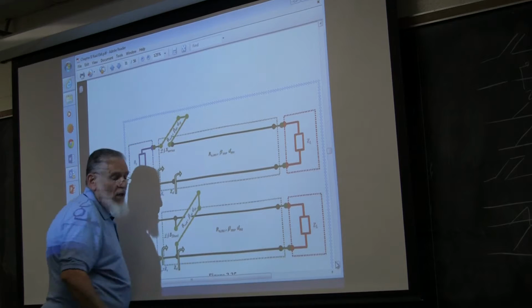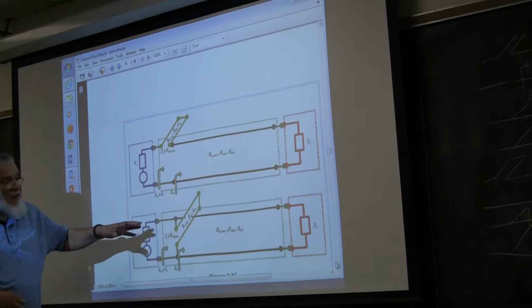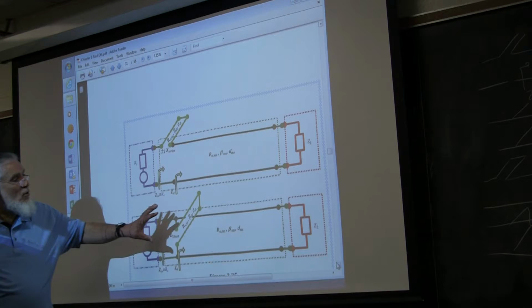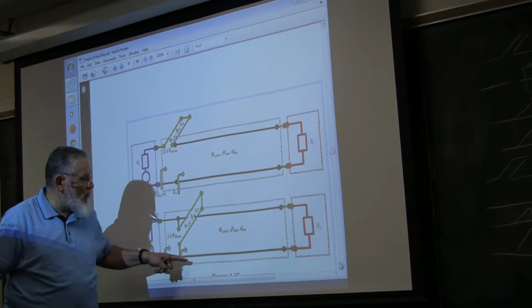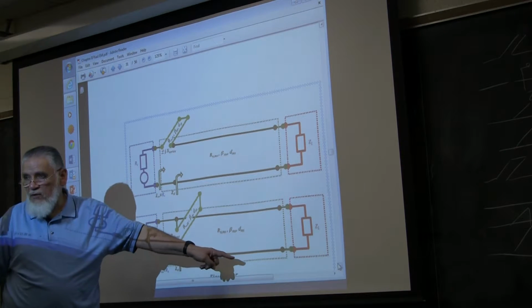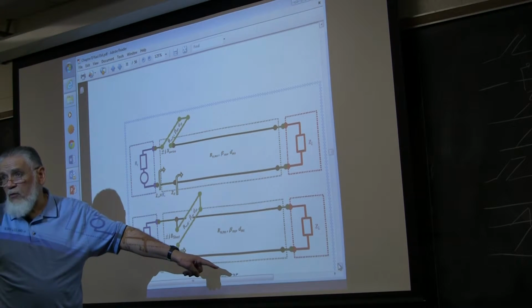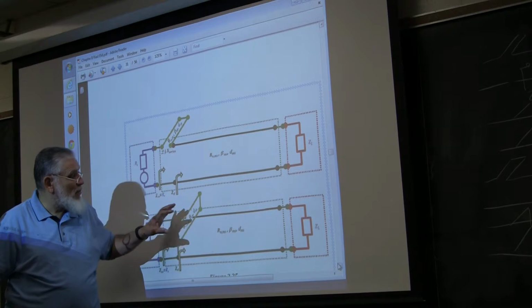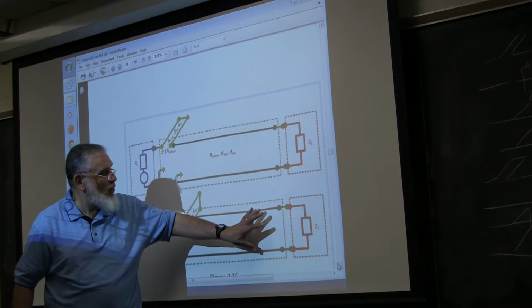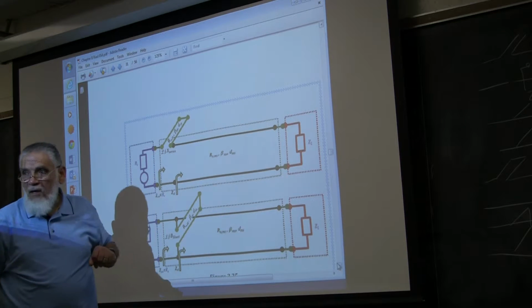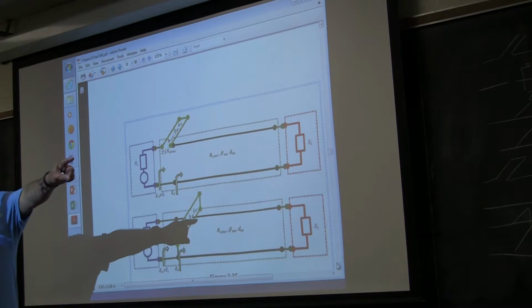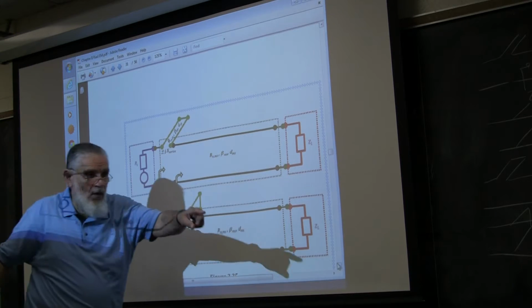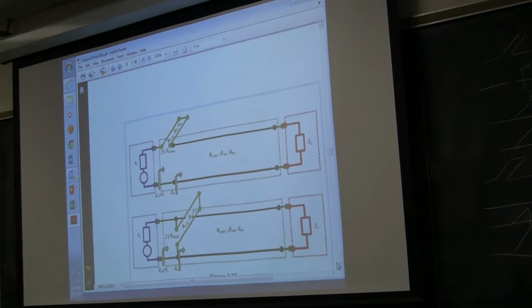Now, this distance here is typically very short, right? Although I'm showing it kind of far, this stub is placed as close to the load as possible. As you know, the impedance here repeats every lambda over 2, all right? So a better picture of this is obviously to put this somewhere in here and show this one here, the maximum. So your source will be sitting somewhere, and your load is over there, and we come as close as we can to the load and put that stub.